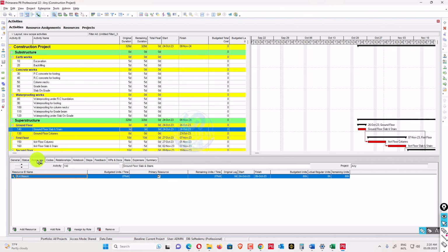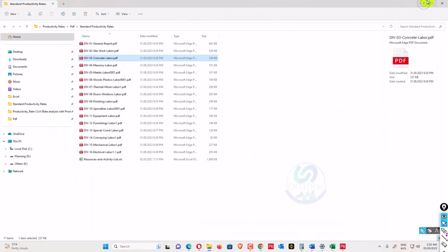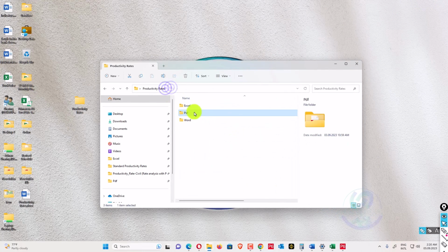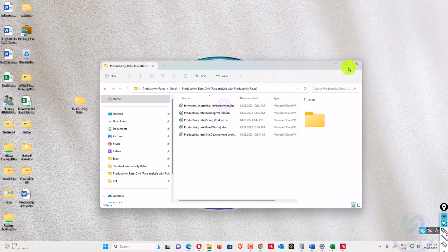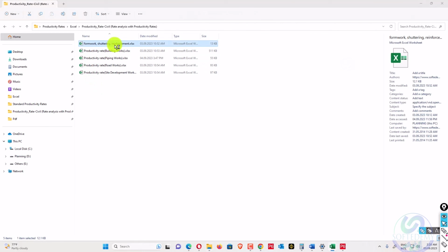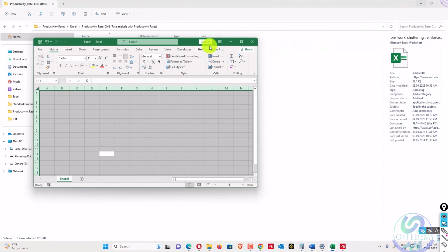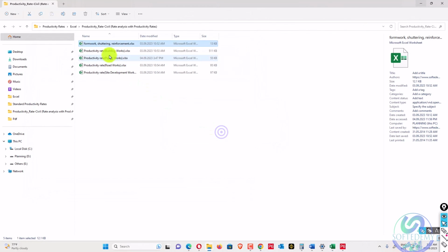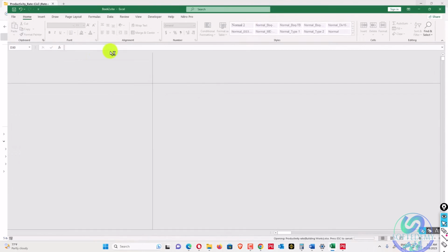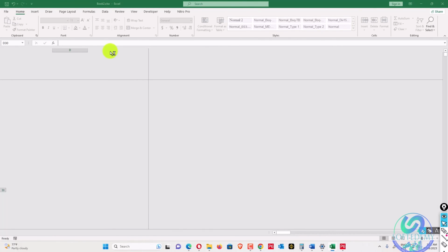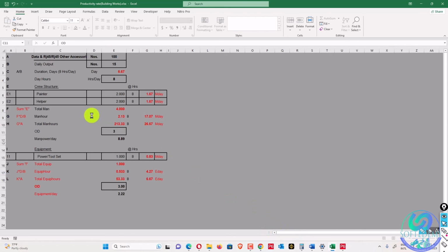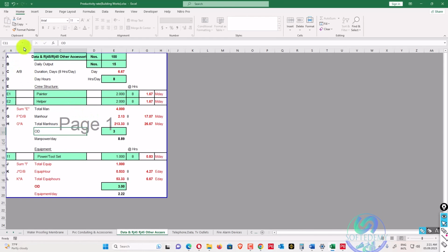And in the BOQ, your rate analysis has been given. Like in my sheets, there is a rate analysis. If I see here in the PDF sheet in Excel, in their civil rates, we have formwork and shuttering work, reinforcement, and building works. In productivity rates, we applied this for our rate analysis, and we bid for a project, maybe an EPC project, but we can consider that we have some quantities. Before bidding, we calculated each quantity, so this productivity rate we have used.